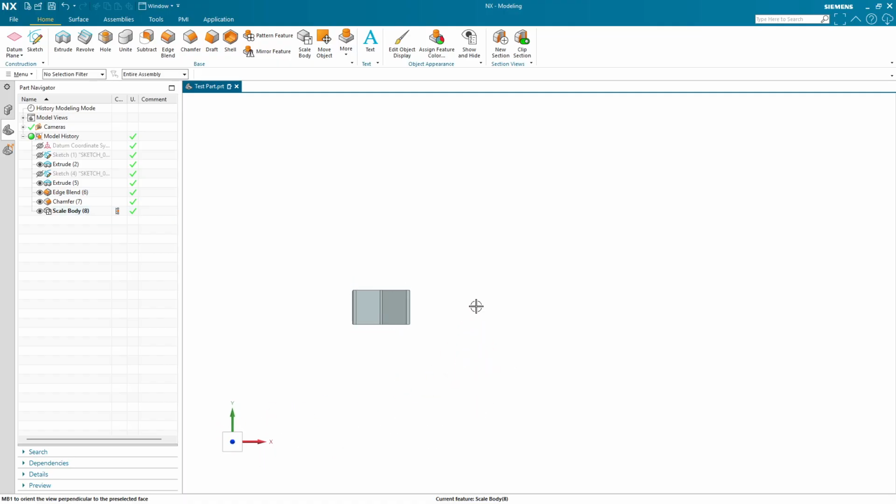So we need to put an axis of revolution where my mouse right now is. So we need to specify a straight vertical line out here, right in the center of this part, and then use the revolve command to send this around in a circle about that axis. So to get that line, and to make sure that that line is actually on the center of this part, not on the front or back face, we're going to make a new plane.